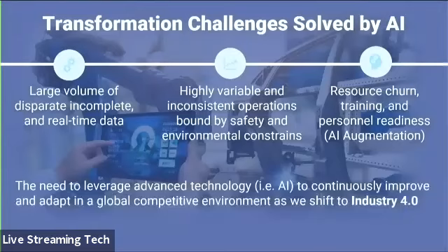So you can extract dynamic information, you can extract patterns, you can extract many things, and AI can take, let's say, 5 years of data and build a model for you, right? So it could be a static model, or it could be a dynamic model. In our case for APC and RTO, we need a dynamic model. Also, if you use deep learning, if you use the right algorithms, we can capture the dynamics of the process, not only the relationship from input X to Y variable, but X to Y in the context of time. So that's very important. And also multivariable. So not just one input to an output, but multiple inputs to multiple outputs, or basically a group of models assembled together to capture a process.